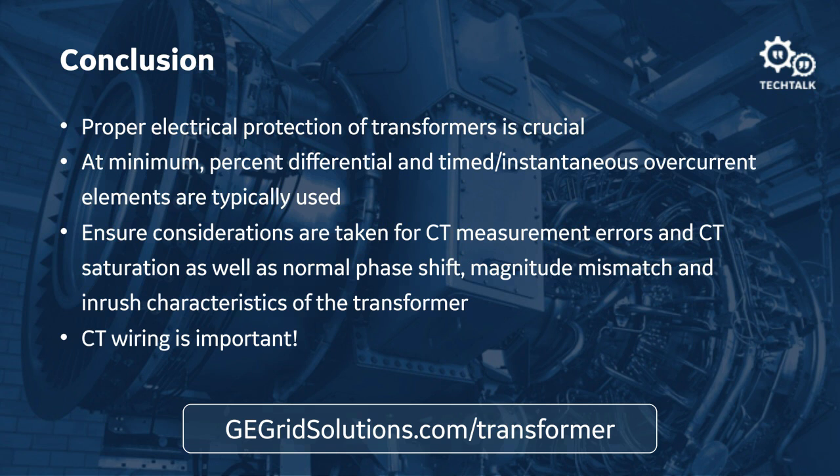Is the IEEE tool for CT saturation free, or do you have to buy it? It's free. If you just Google IEEE CT saturation tool, it should come up pretty easily. Again, that one's just a spreadsheet file as well, so you can save it, open it on your computer, and test it out.